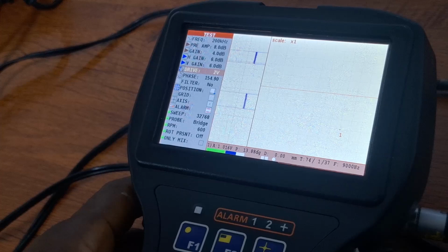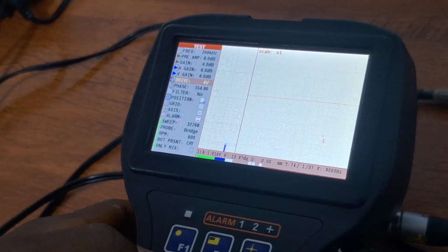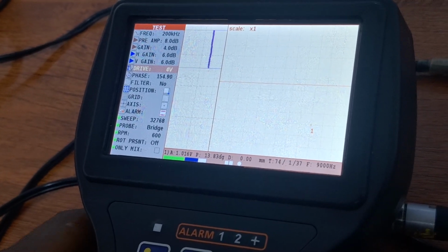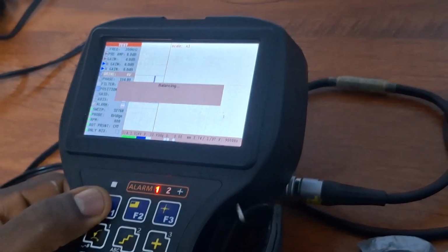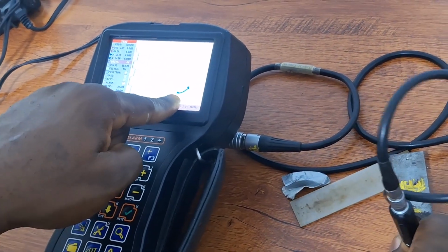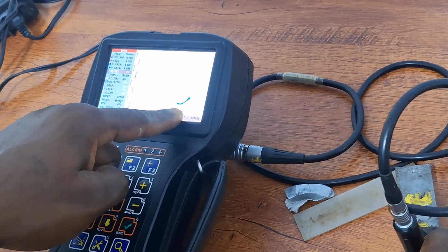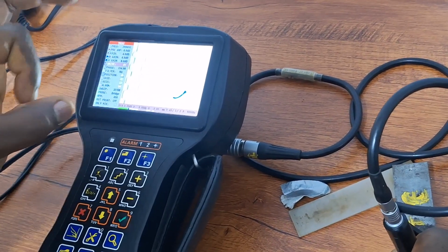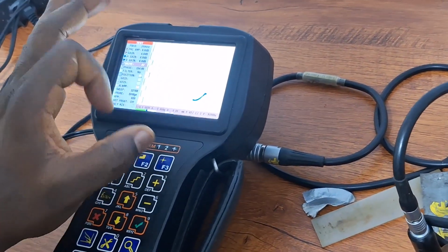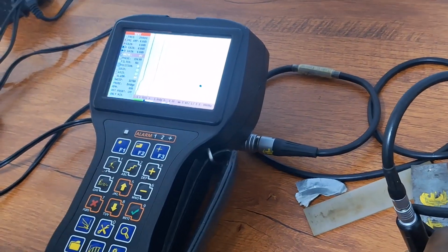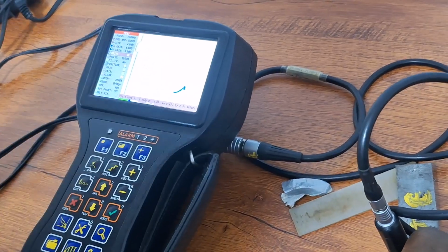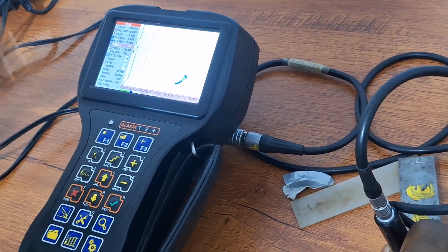We can stay in between. Where you are not so sure, be at the middle. It does not have steps, so we have 2, 4, 6, and I can stay at 4. Let me balance again and see how that affects. If you see, it's not as rough as it was initially because we have reduced the drive voltage. Anything that increases the current is ultimately going to create more noise. The more force, the more noise, the more voltage, the more noise, the more gain, the more noise.